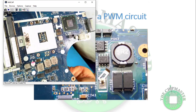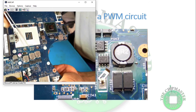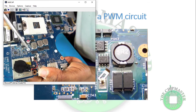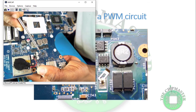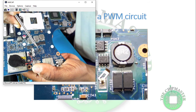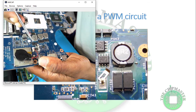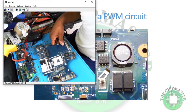As you can see, it's close to the CPU power supply, so these are going to power the CPU, as the integrated graphics supply and the core supply. So 2 MOSFETs, upper and lower, a coil and a filter capacitor, and this is the PWM chip here. It's the same. To know if this is an upper and lower MOSFET, normally I just use my multimeter.